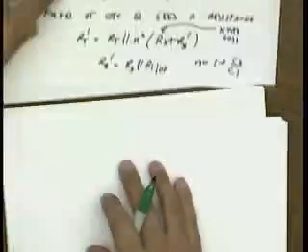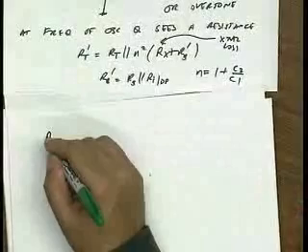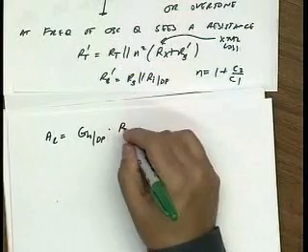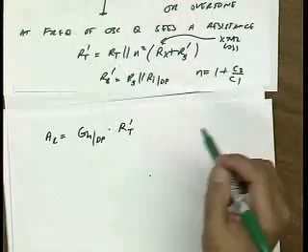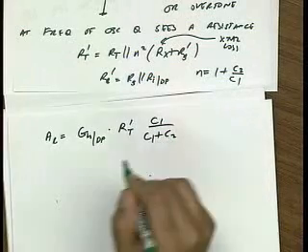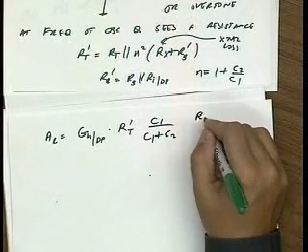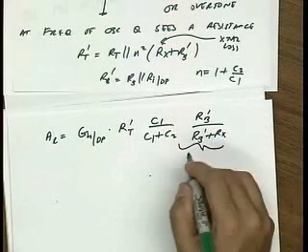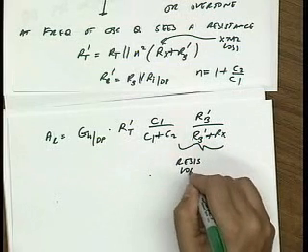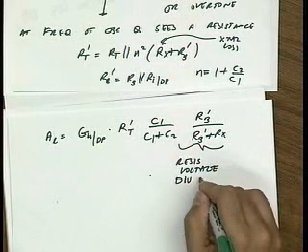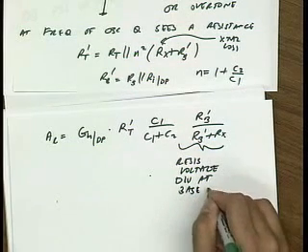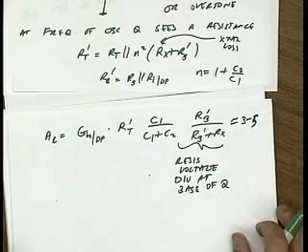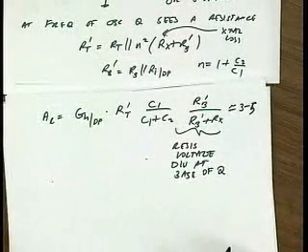So the loop gain at resonance is the small signal GM of the differential pair, times this tank impedance RT prime divided by N, multiplied by this additional factor, which is the resistive voltage divider at the base of Q1. And again, just as before, we designed this to have an initial loop gain somewhere between 3 and 5. Okay?